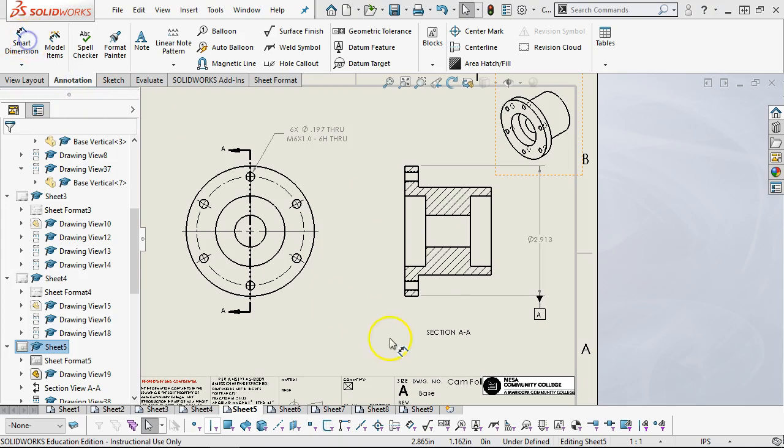All right, so if we go back to the baseline dimensions, we'll do the overalls. Can apply the radius, and in this case, we'll just say it's typical. The other thing is it doesn't need to be 3 decimal places by any means. All right, it's not a controlled radius, so we want to leave that as open as possible. And then we need a center line. I'll go ahead and accept that and pull it through.